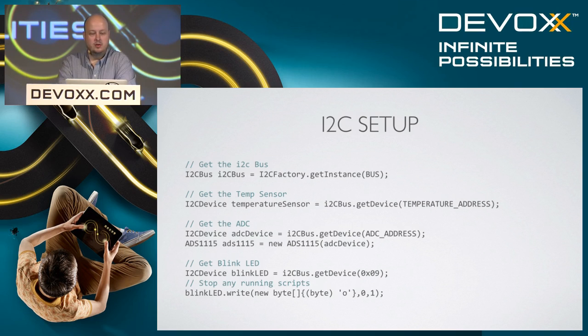So once we've got that, we can open that one up, and then we're doing the same for the analog to digital converter. I have a class here that wraps the I2C device for the analog to digital converter and has some of the internal knowledge about which registers to read and write and how. All of I2C is generally done in unsigned bytes.